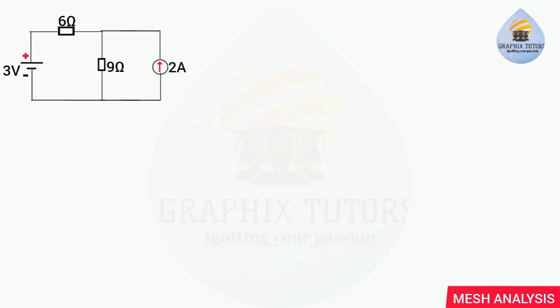Now let's assume that this is mesh 1, we'll call it I1. This is mesh 2, we'll call it I2. Or we can call it loop 1 or loop 2, whichever you want to choose. The current flowing on this part here will be I2. So let's follow the direction of the current. 2A is flowing in this way, so I2 is going towards this direction. Now when I2 gets to this point here, let's call it point B, which is a node, it splits. Meaning that I1 will be going towards this direction, and I3 will be coming down this way. It splits into two, one going down and one going towards the left.